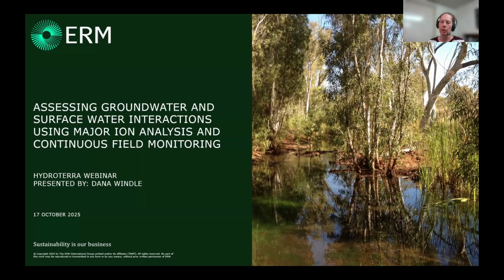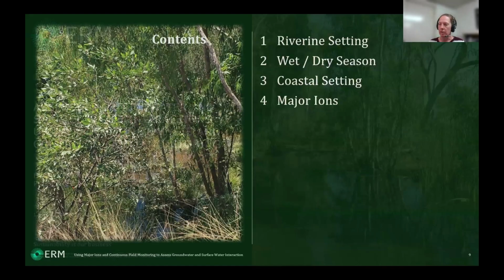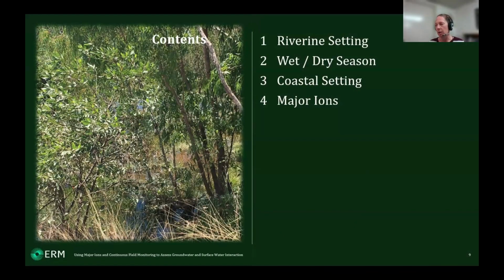Some of you will already know that using major ions is a particular passion of mine, and I'm also a very big fan of using continuous or high resolution monitoring such as dataloggers and telemetry to measure level, pressure, salinity and other parameters. I find that these are really simple and often cheap tools, but they can be really powerful.